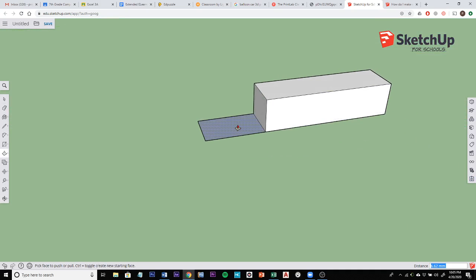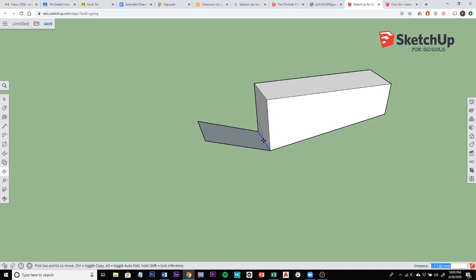So the next thing I want to do is create a slant from here to there, but I want it to be a solid. The easiest way to do that would just be to basically pull this line up to meet this line, and that would slant this surface. So let's see what happens if I do that. Click this line, use the move tool, grab here, and look what happens. It's moving every line that's attached to that line, it's moving it with that line. So again, this is not what I want to have happen.